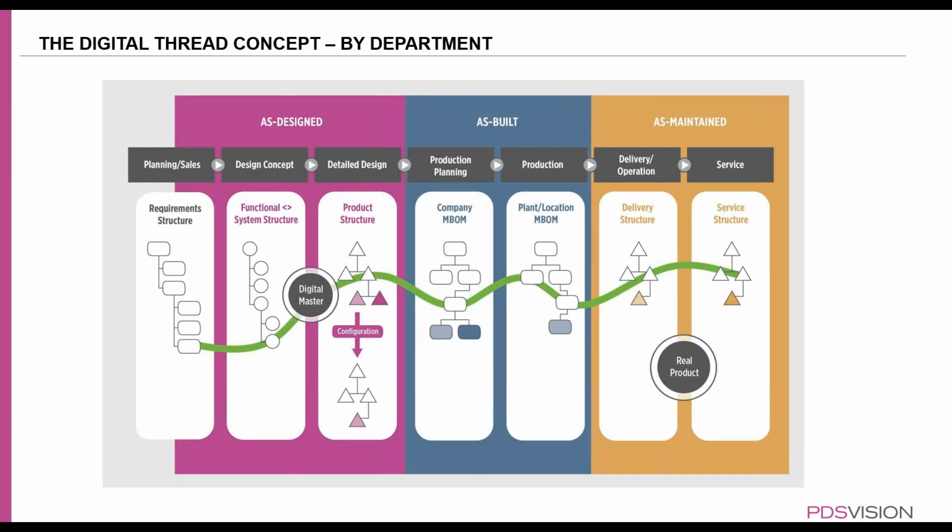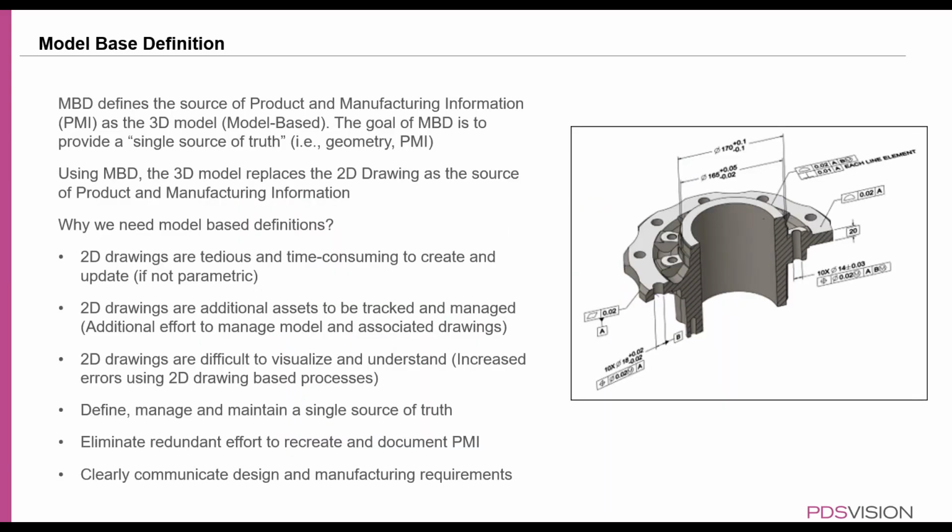better as well. Okay, so then we go to the 2 slides that I prepared for the topic for today, the model-based definition. I think the important thing here is that with Creo Parametric, the saying has always been model-centric, and I think model-based definition fits into that quite well, where we have one single source of truth. If you think about it, you are designing a part, all the information is there, and then you would go and create a 2D drawing of that component. So all we're saying now, if you use model-based definition, is that all that information can be captured in the 3D part itself. If you need to share information, normally at the moment you would send a STEP file or IGES file and the PDF of the drawing. As soon as you send that to somebody, it's not linked, even if it's in the organization or outside of the organization.